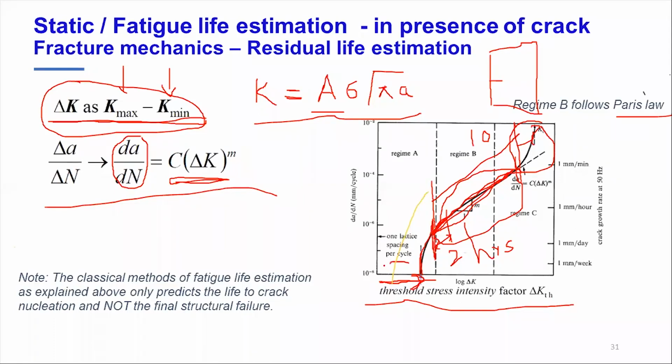If you have a very small crack present here, in this zone, stress also plays a role, but what you have to focus on is that the crack length is so small that your delta stress intensity factor is within this limit, below this. If this is the case with the combination of crack length and stress, the crack will not propagate during your life cycle.